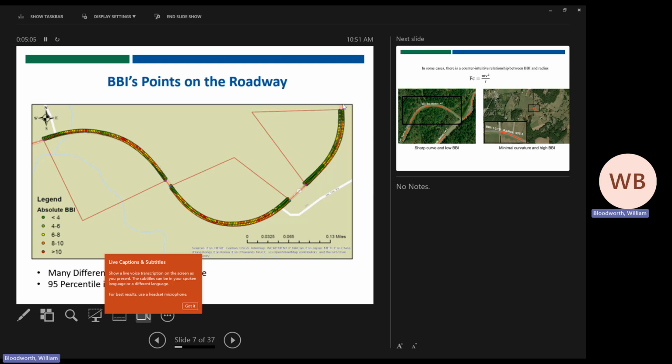So nearly the maximum. What we didn't do is take the maximum value. That's because if you hit a little bump or a stone on the road, something like that, the ball bank indicator reading shoots up, and it's historically known for having lots of outliers. So definitely make sure you're not taking the maximum value if you see that.